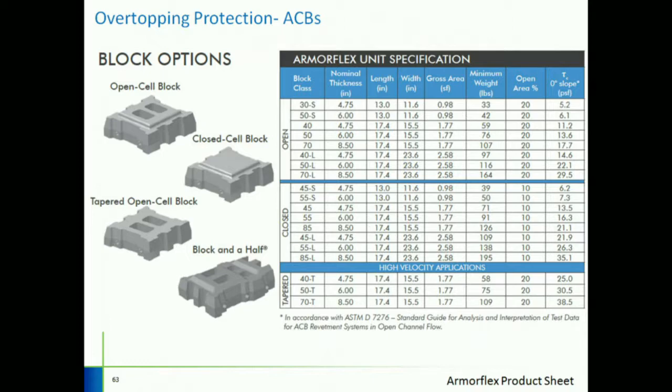Steps involved in the construction. We clear the slope, and then we lay down the geotextile, and then we bring the ACBs and place them over the slope, and then we anchor it down.